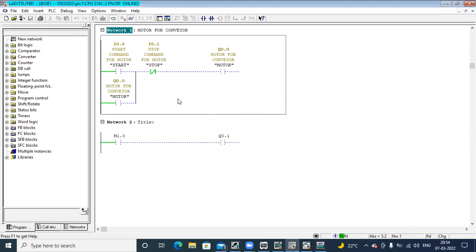Next, our next topic is flasher byte. Flasher means flashing, on off flashing for a predefined time, like fast flashing, slow flashing, medium flashing, right? So there will be LEDs on a panel that will be flashing for showing the status of your logic, the motor is on or off, or if temperature has crossed the limit, okay? So for such a process, we are setting the flashing.